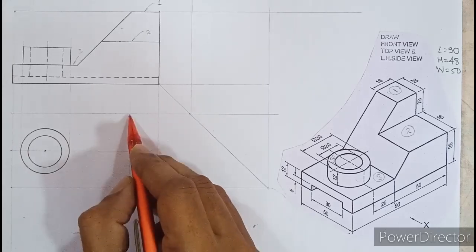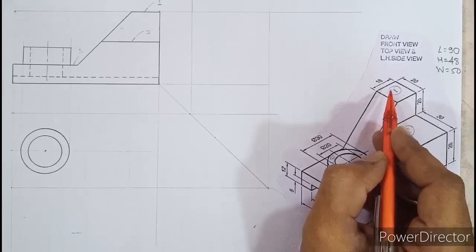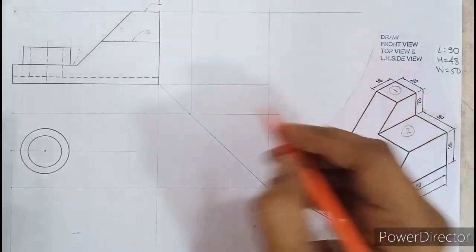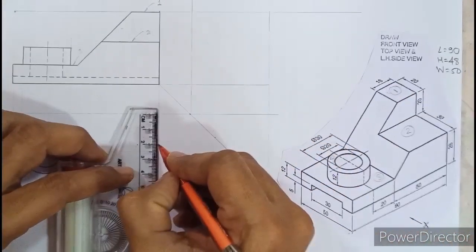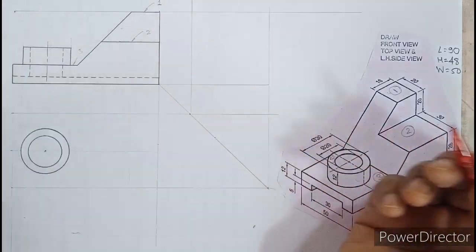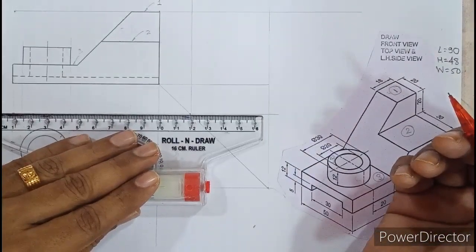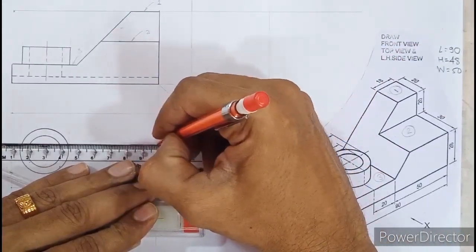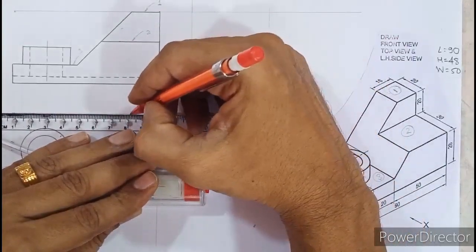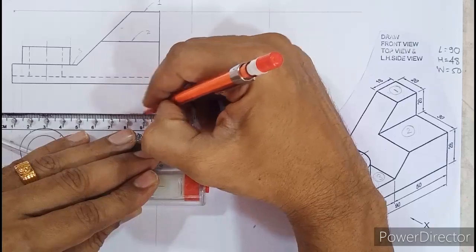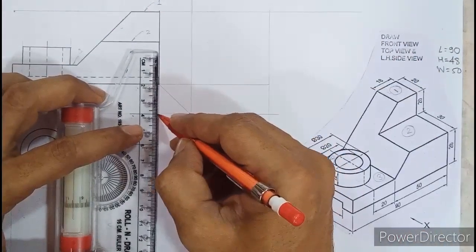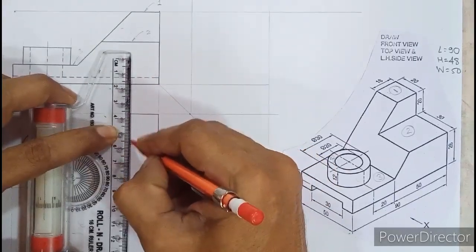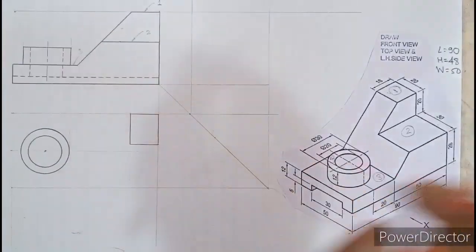But what about the width of surface 1? So go back to the question. You have projected 18 from the front, right? So the width is now 20. So we need to mark 20 from here. Okay, and we will darken the rectangle. So I have darkened the rectangle over here. Let us darken this from all the four ends. This will give us surface number 1, which is seen as a rectangle. So surface 1 is ready.